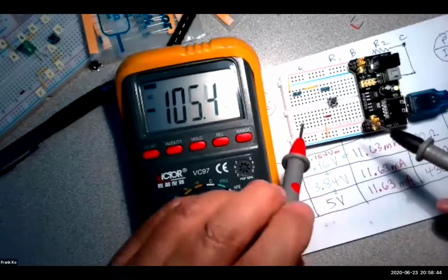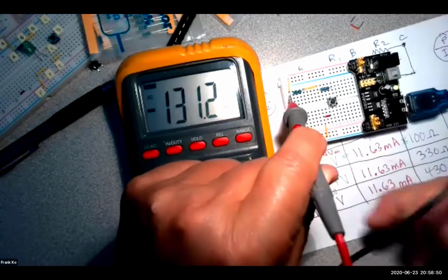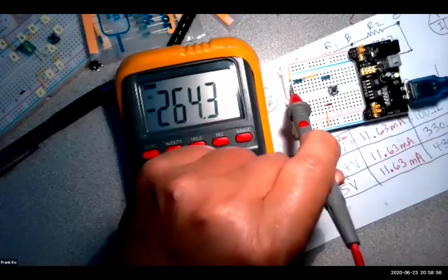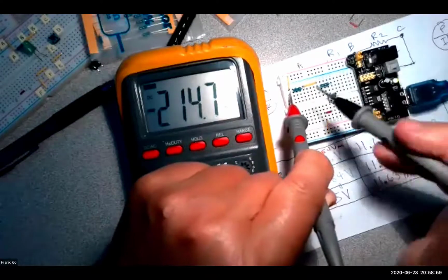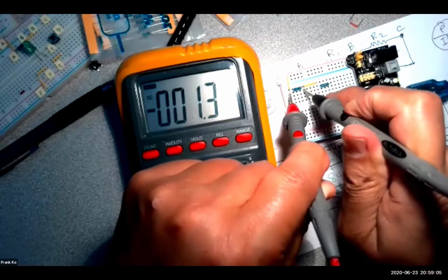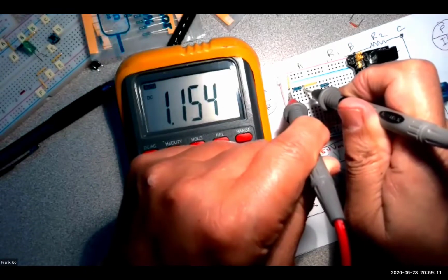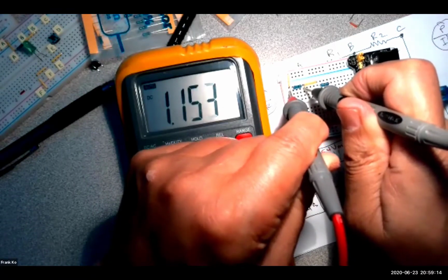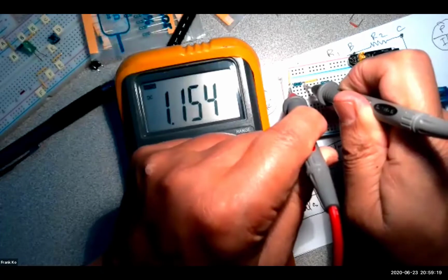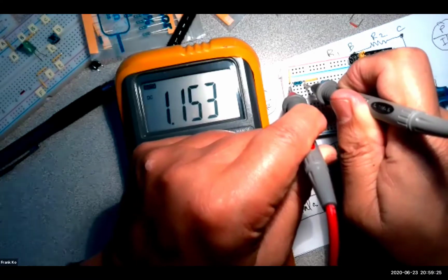You're going to stab the red probe right to the end of the wire where it attaches to the board. So I'm just stabbing right down on there. And I'm going to get this probe and I'm going to stab on this side of the resistor and hit the switch. When I hit the switch, I end up with 1.153. This is pretty much what I had a moment ago, 1.154, 1.154. Fluctuates between 3 and 4. Is this basically the same?